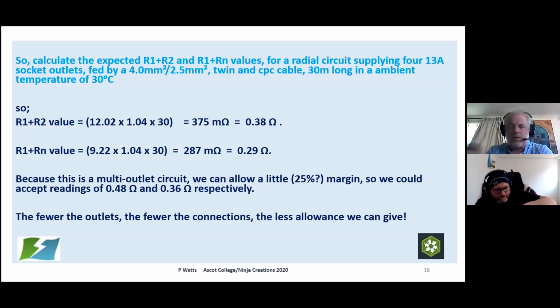Okay, so if you've got lots and lots of socket outlets, then yeah, you're possibly going to have quite an increase or possible increase in the resistance value. It's every single point of utilization is a point of potential increase in resistance, isn't it? Yeah. Every termination, every connection point is a point of increased resistance. Okay. And by the way, your connections, you're breaking the conductor and you're putting it into a thing which may have a slightly different resistivity. So that's actually perfectly normal, isn't it? Yeah, and people do, as long as it makes sense with the values.